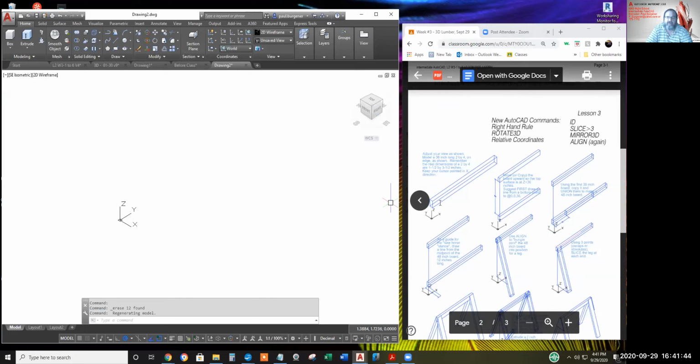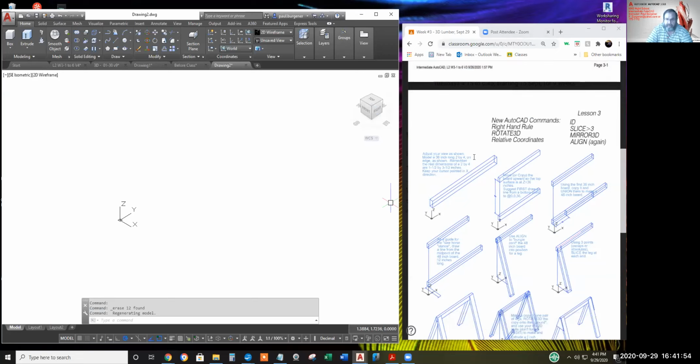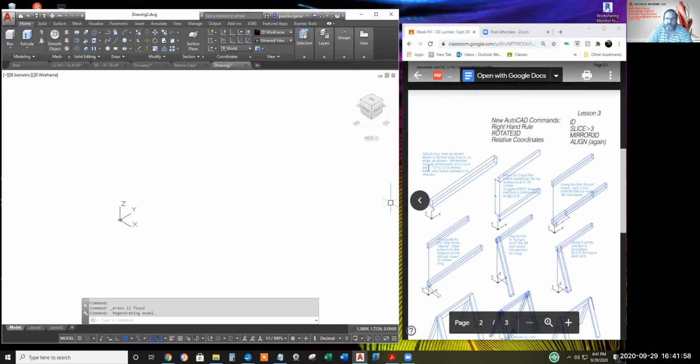And draw yourself a box or a rectangle to be extruded that is 3 foot long, made out of a 2x4. Now, like it or not, a 2x4 is really 1.5 by 3.5 after the sawmill blade cuts through and the sander takes off some. So let's